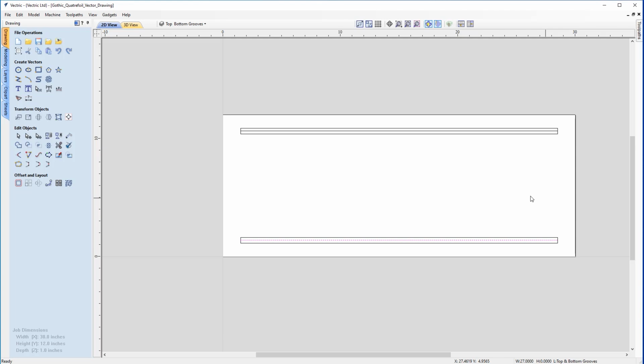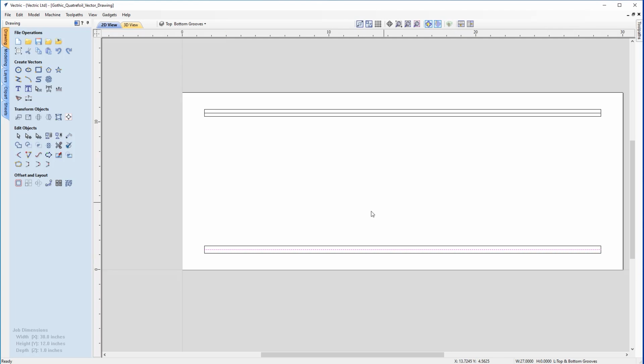There are a few ways you could go about doing that, but I think the most straightforward here is if we shift and select both of the lines, and then click again to put that into transform mode. And you'll see now to the right and to the left these sizing points or handles. So if we hover our mouse over this and left click and hold that down, we can just stretch this end out and do the same to the other side, just extend it past there.